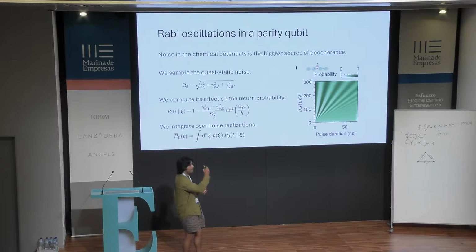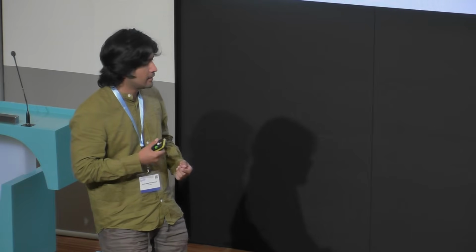If you go farther from resonance, it means that the coupling is weaker between the two chains. But it means that you are also less sensitive to noise in the middle dot. If you are far from resonance, at that point, the limiting factor are the chains themselves. So if the limiting factor is the chain, going to a longer chain will improve that limiting factor.